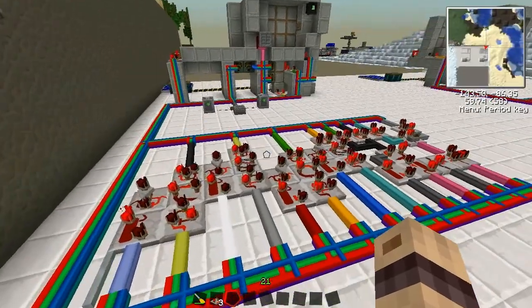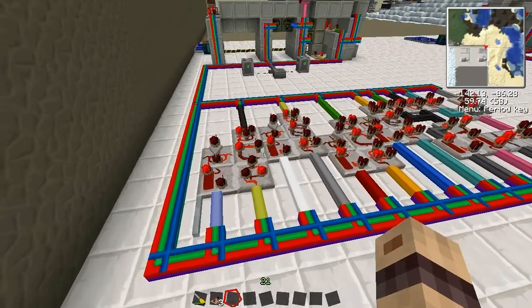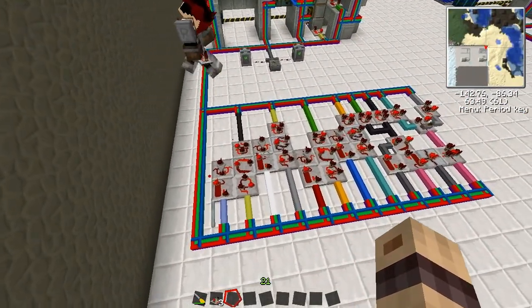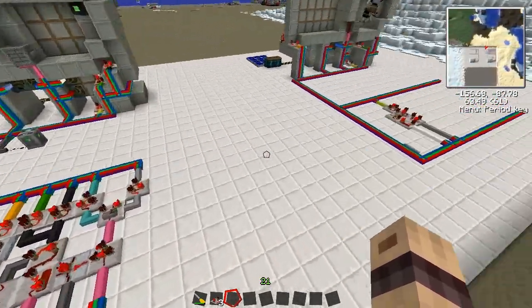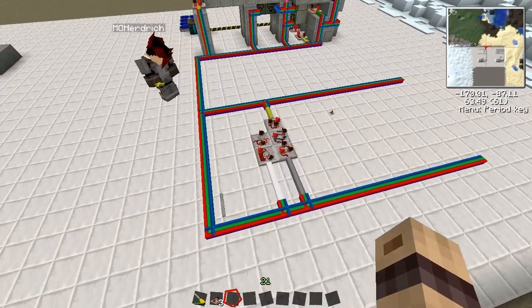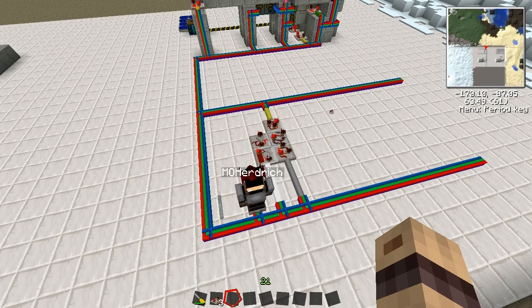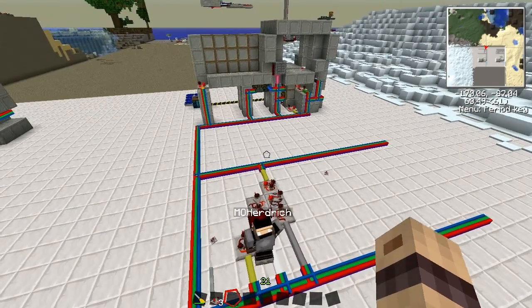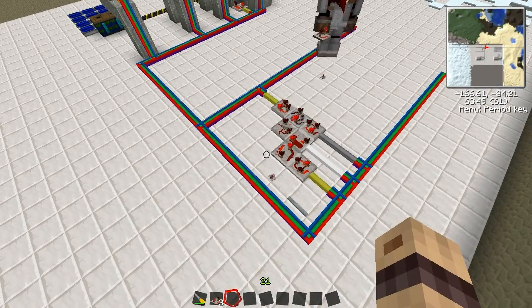So would I be right in saying that most of this system is a repeat of that circuit there? Yeah, exactly. This is 1, 2, 3, 4 of those in a row. Because now we just feed the yellow signal, this one, the sensor signal, back to another RS latch. No, that's the wrong part. It is this one. And we toggle another RS latch this way.